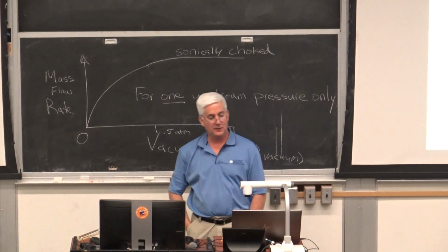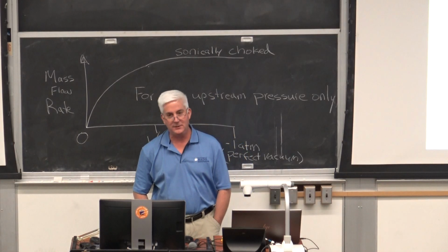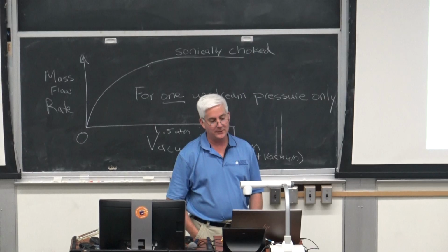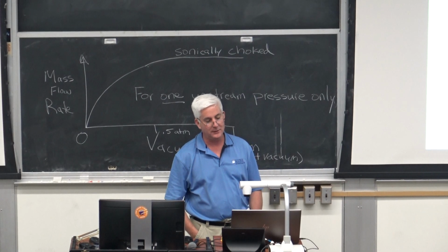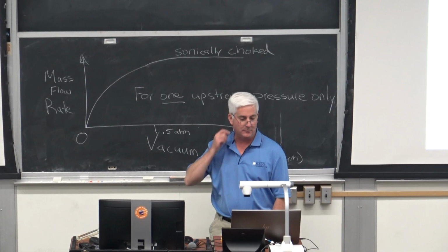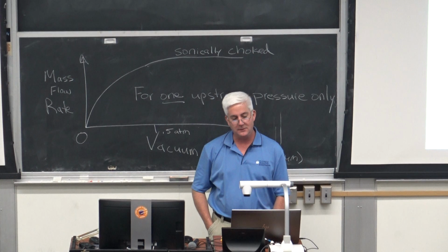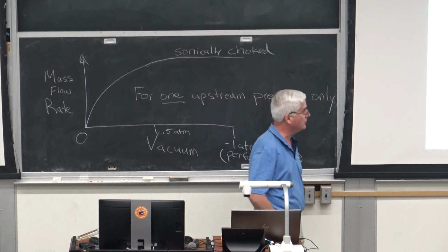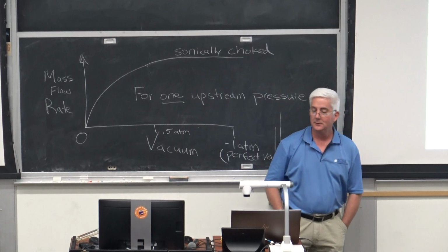Okay, so Mav's Darkstar is cruising along at Mach 10. Some air molecules are being brought to rest against the windshield. What's the air temperature? Assuming Mav is at 80,000 feet, standard Blackbird flight altitude, and the air is minus 62 F or minus 51 C, which is the standard temperature for 80,000 feet.